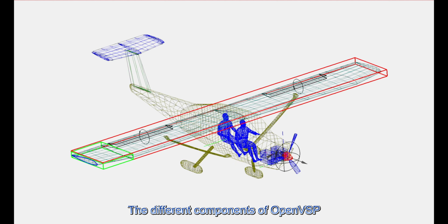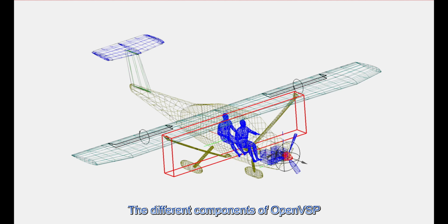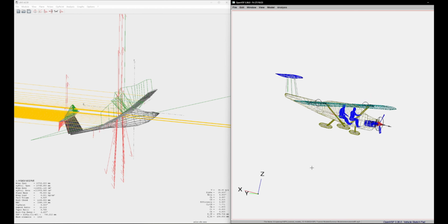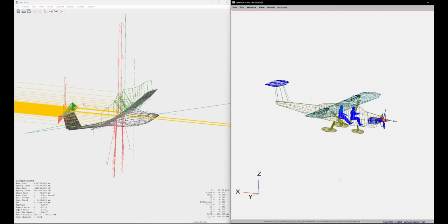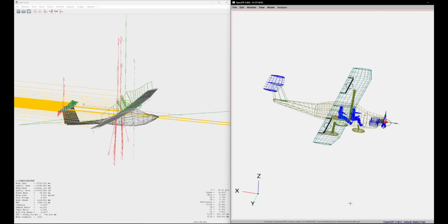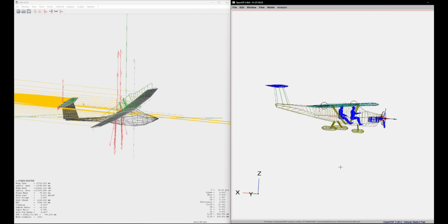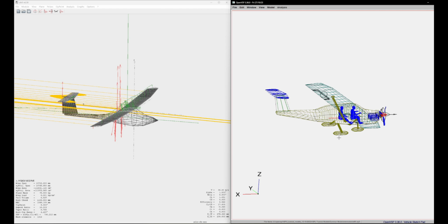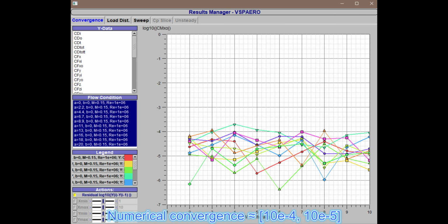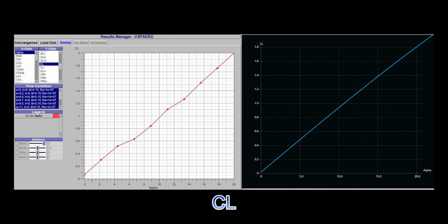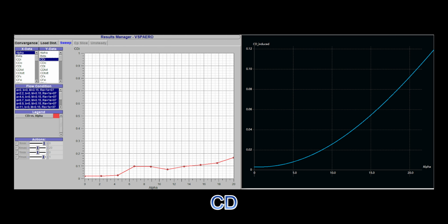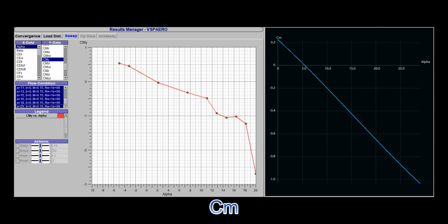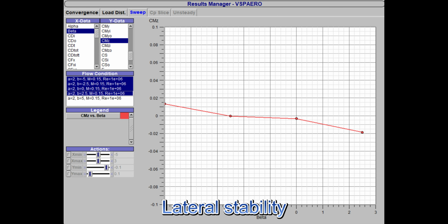The structures and weights of the pilot, electric motor, landing gear, augmentation devices, and battery are also represented. This more complete model is then subjected to aerodynamic and stability validation, serving as a double check after switching modeling environments. By comparing the full aircraft results simulated in OpenVSP with those from XFLR5, it can be seen that the values of CL, CD, CM, and stability remain essentially the same.